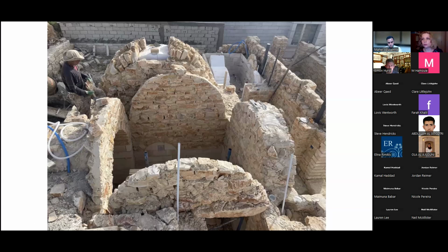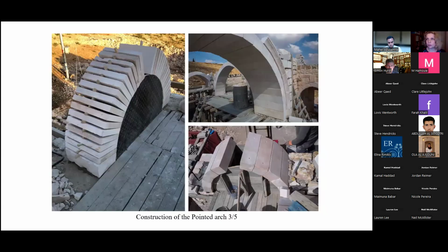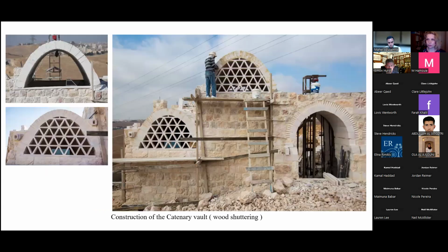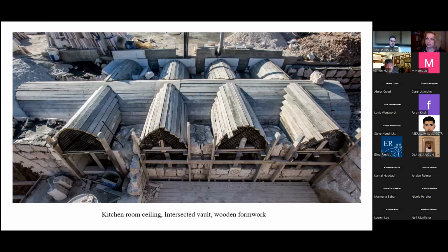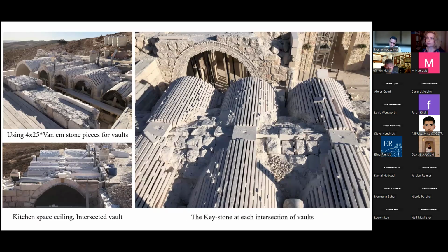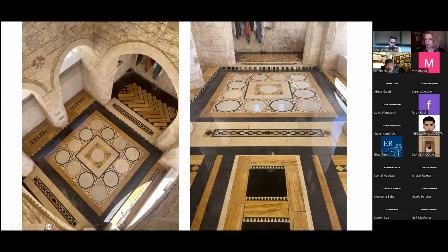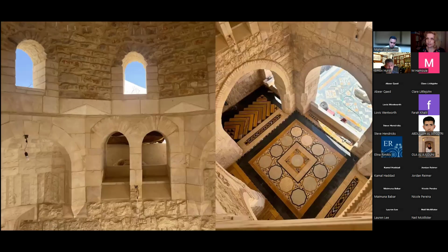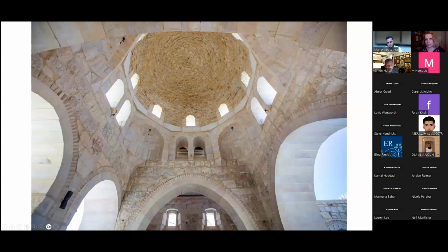Yes, I would like to add something to what Mohammed said. Indeed, INTBAU had a long time ago a revised Venice Charter, and now it is 20 years since it was released, and we are planning with Matthew Hardy to have a revised Venice Charter, because a lot of things have changed meanwhile. And we have somehow to challenge those interventions with modern materials, which are contrasting with the existing fabric, because from this point, a lot of problems start. Not only aesthetical, heritage related, but also, as Claire said, the new materials are of different quality. They don't behave like the historical ones. And from there, you can practically compromise the full structure if you don't have a good binding of the old and new materials, or at least to behave in the same way.